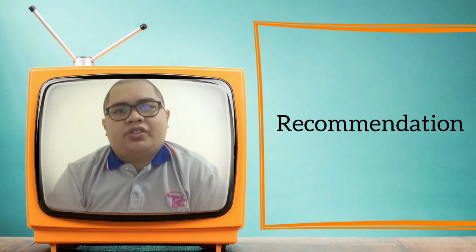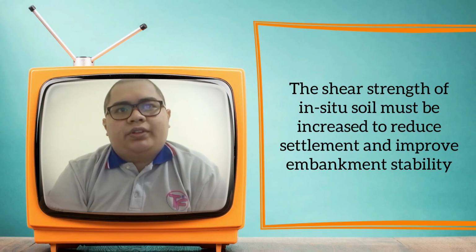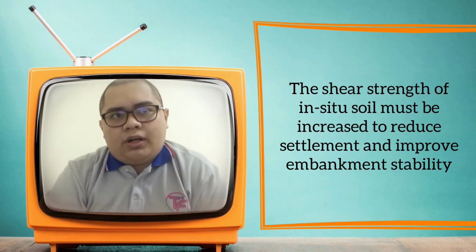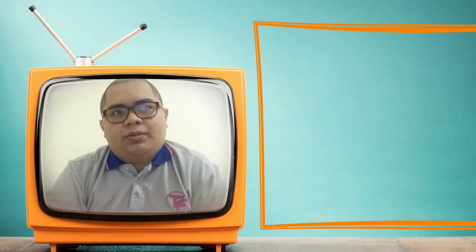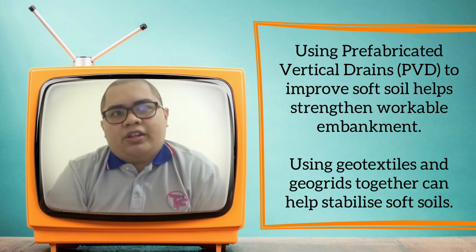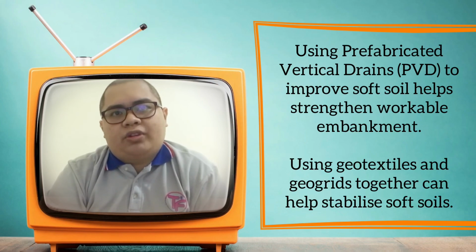For the recommendation, various on-site methods are available to improve compressible soil. The shear strength of in situ soil must be increased to reduce settlement and improve embankment stability. Suitable ground improvement techniques include using PVD, prefabricated vertical drain, and using both geotextile and geogrid together, which can help stabilize soft soil.